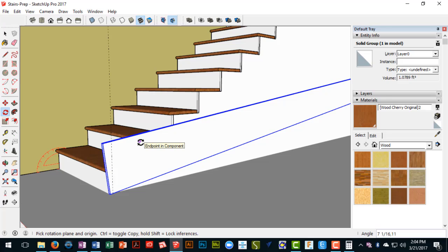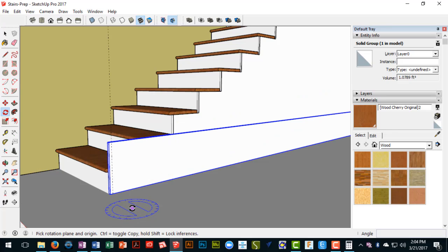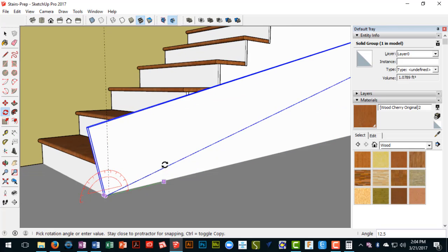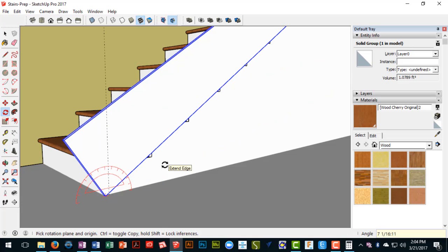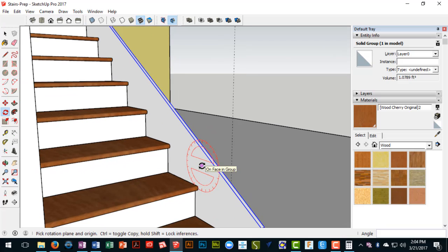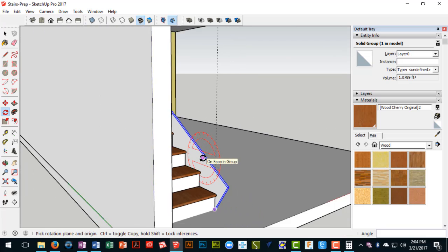And pressed enter, and that did not work. So let's try that again. So we want this to go upward 7 space 1/16. Oh, what I did was comma instead of colon. So I'm essentially doing a roof pitch here. So 7 and a 16th, colon 11, and press enter. And that puts it at exactly the right pitch for my stairs.